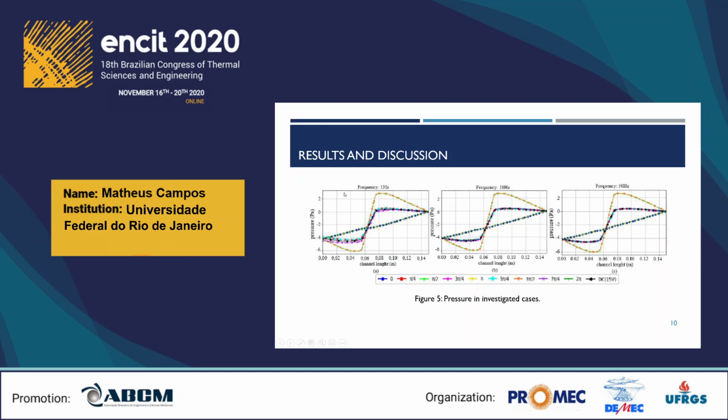Here in figure 5 let's show the results for the pressure distribution along the channel's length. It can be observed that the profile for the AC case matches the one for the DC configuration, although there is that oscillation caused by the applied voltage and magnetic flux density. And while for the current density and the Lorentz force the observed oscillation is symmetric over the evaluated period, this does not happen for pressure, and it occurs because of the inertial effects.